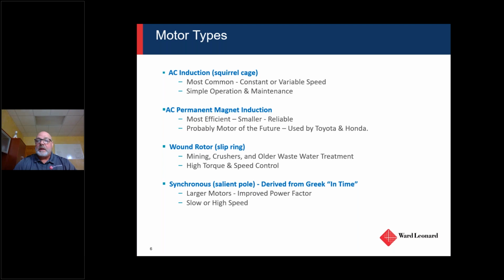They can improve power factor on a highly inductive circuit because you can adjust phase angle to lead and lag. So if you have a lot of motors turning on and off on a main bus, a synchronous motor can soak that up and clean up the power some.